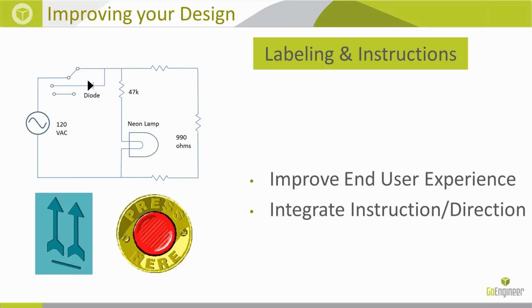So whether it's a consumer product or a component for someone who's assembling a product, you can speed up that process by adding that value, just molding in some instructions or indicators. And just to add real quick, going back to one of the rules from before, you want to ensure you have fillets or chamfers in those regions. So there is an easy flow of the plastics to those intricate areas.